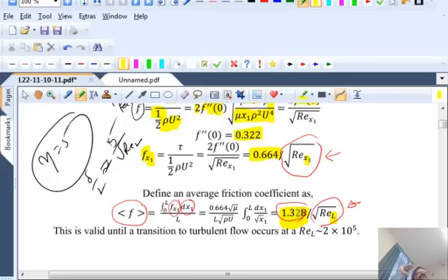So for example, if you take a plate made of naphthalene that sublimes based on the local velocity gradient, then by measuring the changes in the thickness of the plate over a period of time, you can say what the local coefficient is. People have done very careful experiments to measure the variation of the local coefficient with distance, and of course the average one also, the total. And they agree quite well with the theory predicted from this equation.